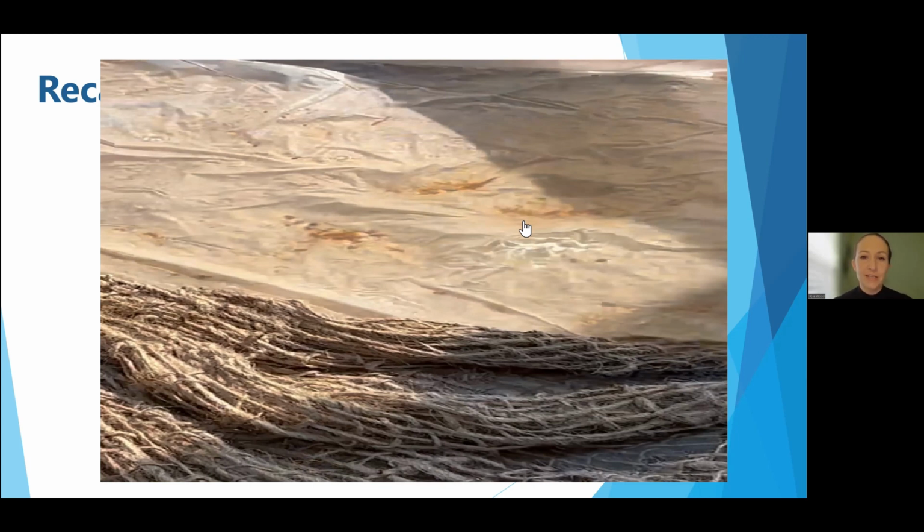There's been a lot of different studies that have looked at those different characteristics of a polymer and tried to predict, based on a specific soil type and soil characteristics, can I use this charge density and this molecular weight for this specific soil type? Although there's been a lot of work done and a lot of people have tested that, pretty much all of those studies have come down to that you have to physically get your hands on the soil sample and the polymers and do that jar testing. So there are reasons and differences in the polymers, but you still have to physically test them to see which ones are going to be effective.